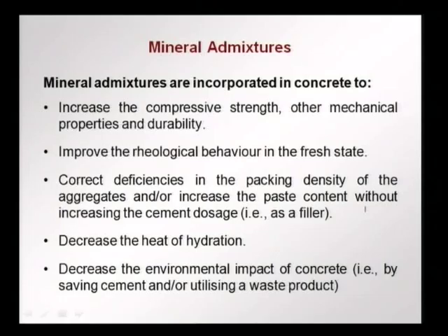When we replace cement or we increase the paste content without adding more cement, we tend to decrease the heat of hydration compared to the case where we would have only cement as the fine material. Mineral admixtures, when incorporated in concrete, also decrease the environmental impact of concrete when we use, say, a waste material like fly ash. This leads to saving of cement, saving of clinker, which needs a lot of energy, which needs a lot of raw material, and on the other hand we use a waste product that is just going to be dumped or thrown away.